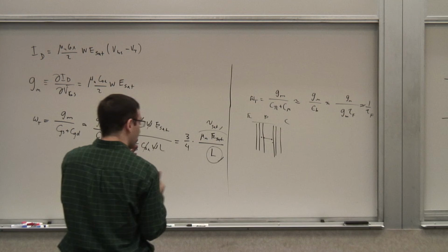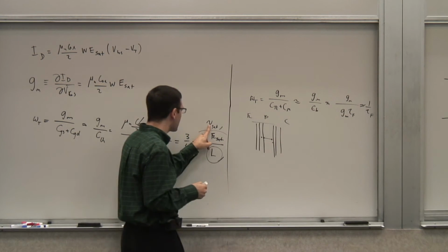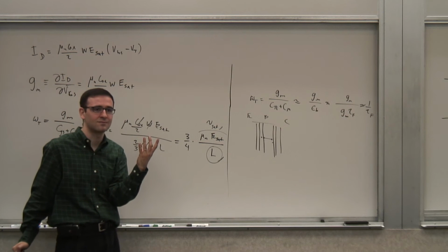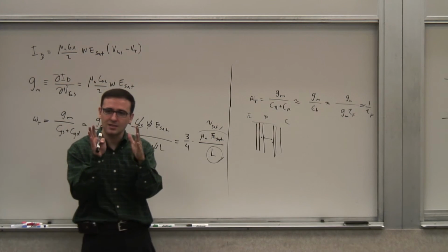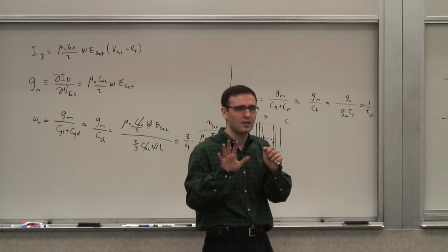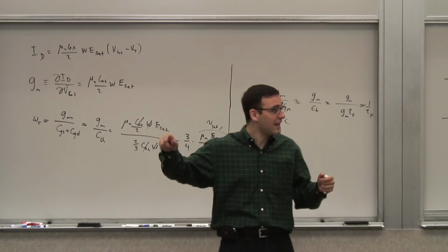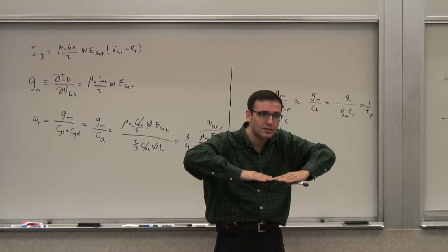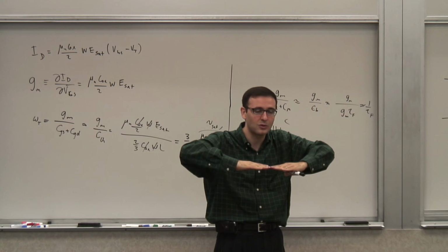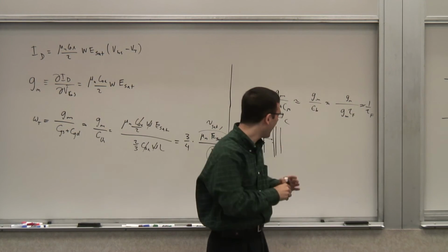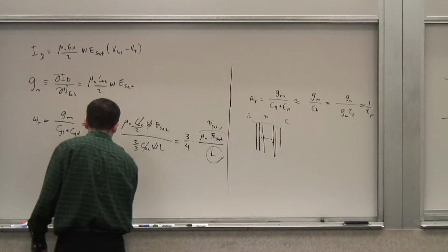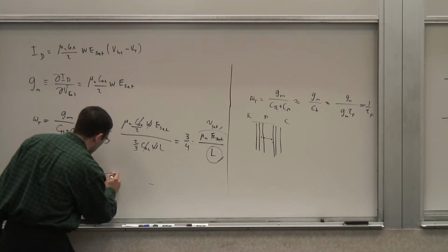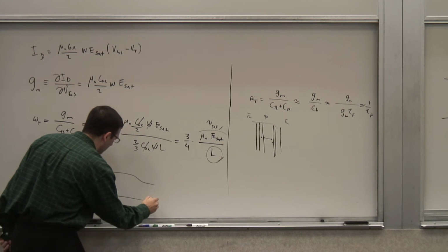Now, it's random thermal movement. Here though, in either case, this case or that case, this is a drift velocity. This is that overlap velocity on top of this thing. Because in a MOSFET, when you turn it on, when you lower the potential barrier, right? We saw that in the energy band diagram. When you're above the threshold, you have an energy band diagram that looks like this. So initially it was high, and then you lower the potential barrier, so it looks like this. So it's N all across.